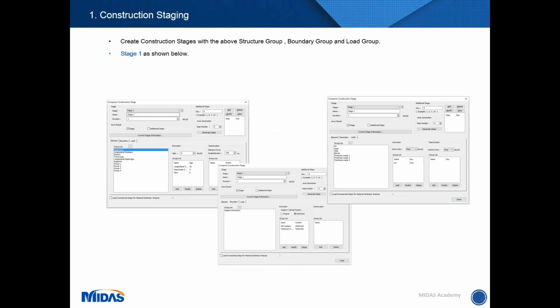So in stage 1, we'll just activate the longitudinal girders, the plain Super-T girders, with boundary conditions of only temporary supports, which would be removed later once we have a single row of bearings set above the pier, and we're just activating the dead load of concrete in this stage.